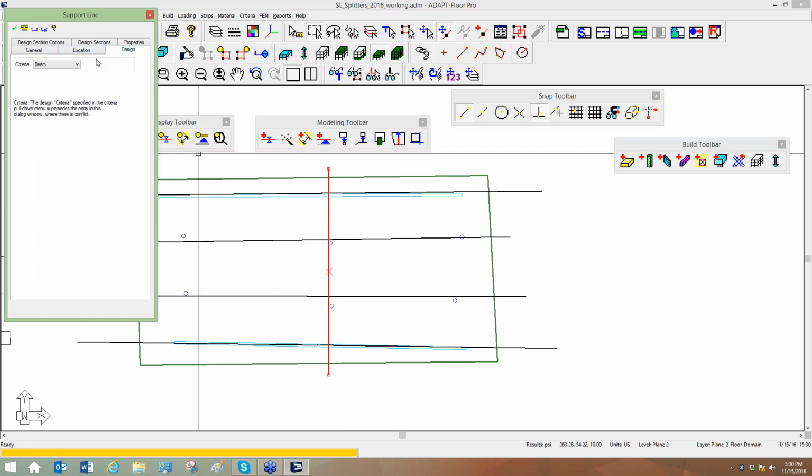Ultimately, we're trying to get both strength reinforcement and minimum rebar in the design. The program doesn't care whether it's one-way or two-way when it comes to strength reinforcing. When it comes to minimum reinforcing, it's going to use different criteria.